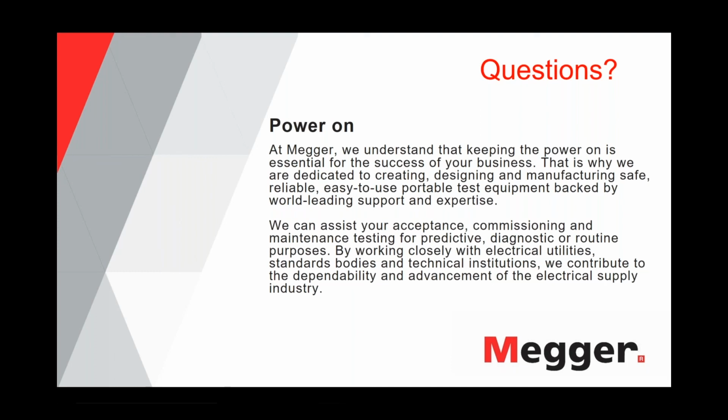All right. While we have you, why does rain affect TD results if the water is not entering the cable? Does water or weather conditions affect measurements of underground cables and conduits? Well, there are two questions in one here, right? One is basically how rain affects it, and rain can only affect an underground cable wherever you have a termination.